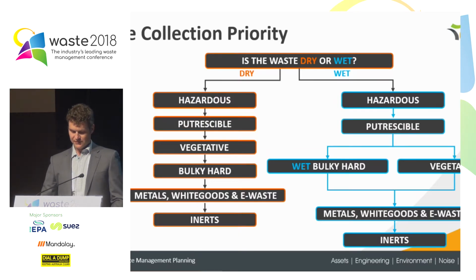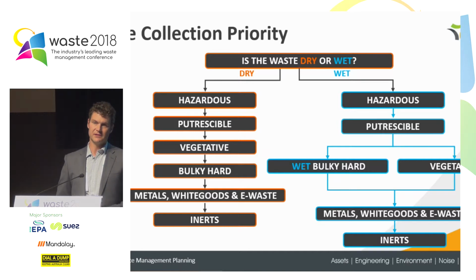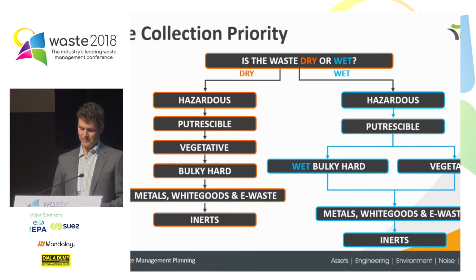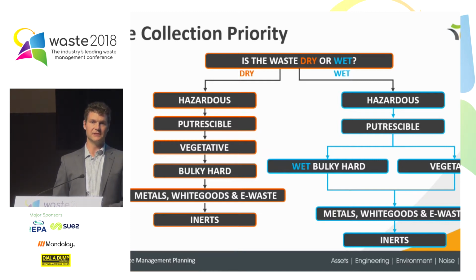But also, what else affects the timing of collections is obviously the types of waste, and it is important to prioritise the hazardous materials first, because they're a public health risk, then move on to the more putrescible wastes, while leaving the inert materials to last. But hazardous wastes are typically managed by specialist contractors who are licensed to do so. So it's definitely important to engage them very early on in the implementation of the plan, so that they're on the ground first and they're securing, identifying any hazardous material.